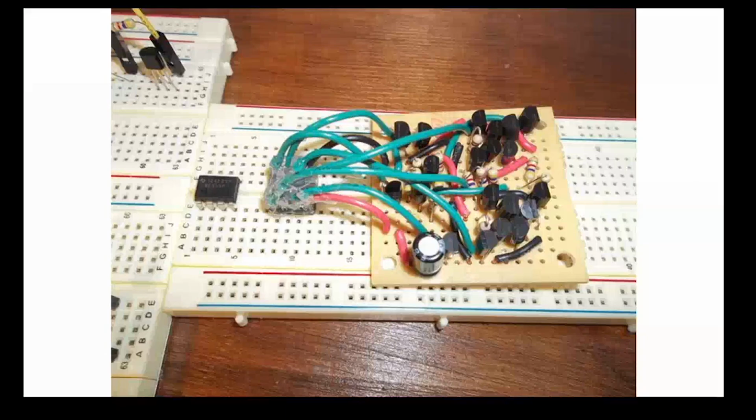So this is one breadboard example I'm giving you. What people do is put various ICs on a breadboard, connect them together, and see how it is working. But this is a very vague way. This is not a standard way, because there might be a lot of noise added due to these long wires. There might be a condition that the components or ICs are not properly connected.